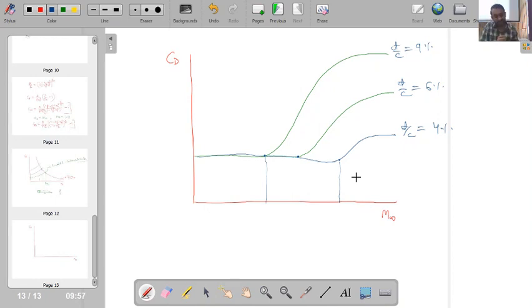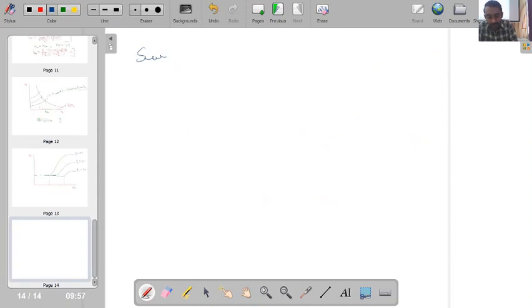The second strategy which is generally followed is called the swept aerofoil structure. What is basically done is that the shape of the aerofoil is swept in the backward direction through some angle.